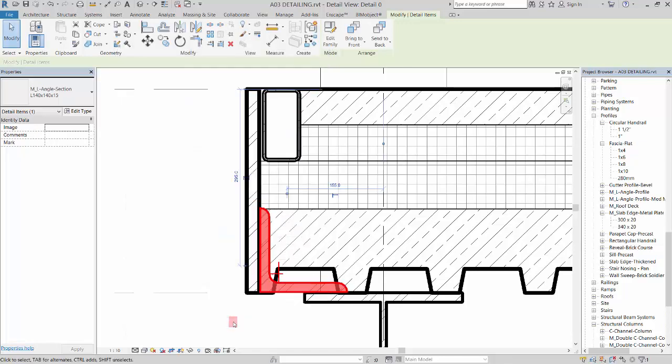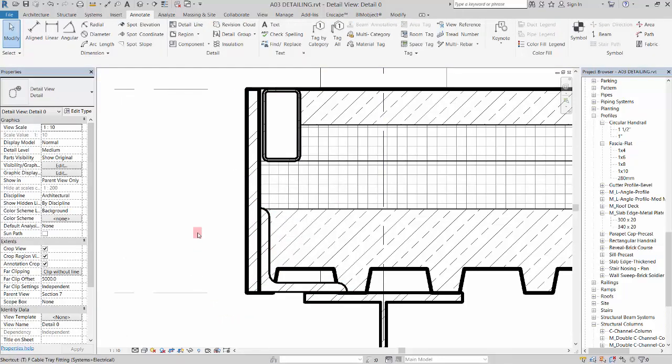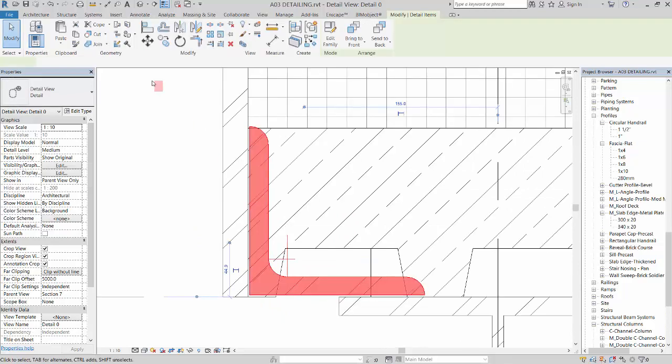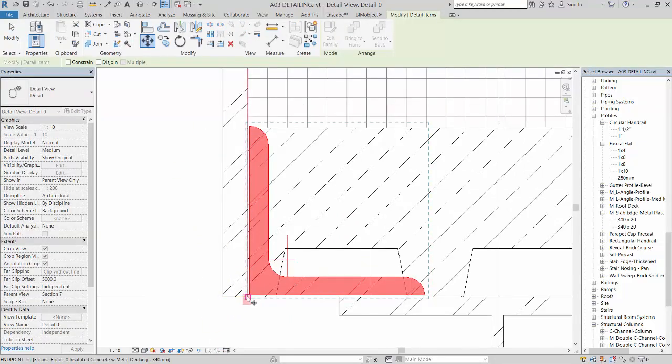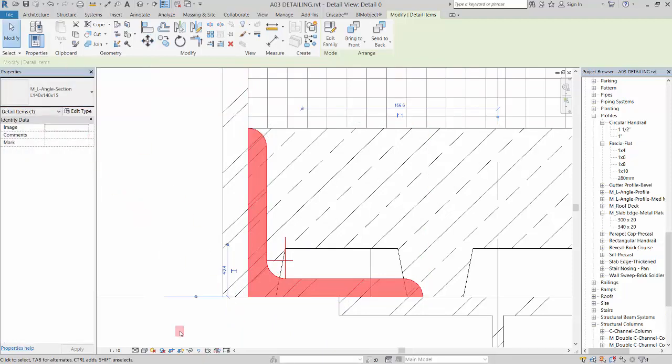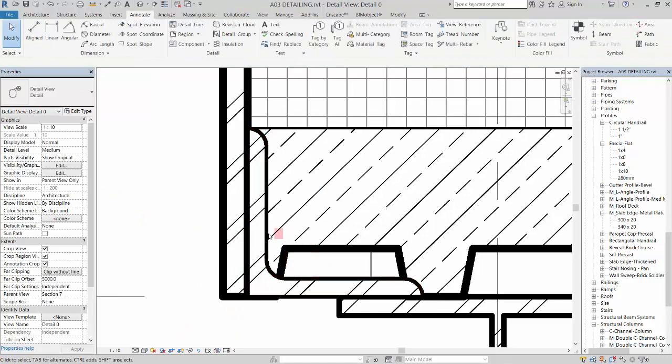And click OK. And then I'll just go to thin line and kind of move that into place. Right? So move it from there. And I'm going to do SE for snap endpoint, and it'll snap to that endpoint. And if I go thin line, there you go.